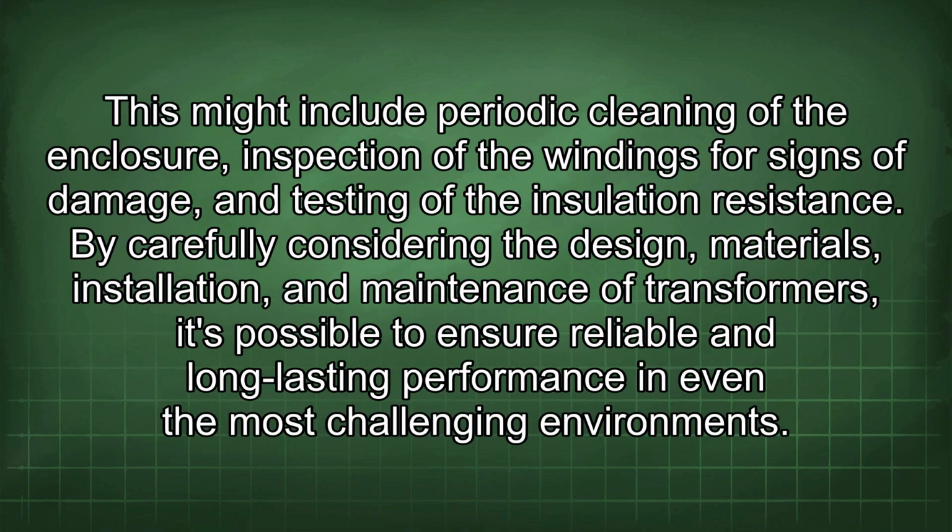This might include periodic cleaning of the enclosure, inspection of the windings for signs of damage, and testing of the insulation resistance. By carefully considering the design, materials, installation, and maintenance of transformers, it's possible to ensure reliable and long-lasting performance in even the most challenging environments.